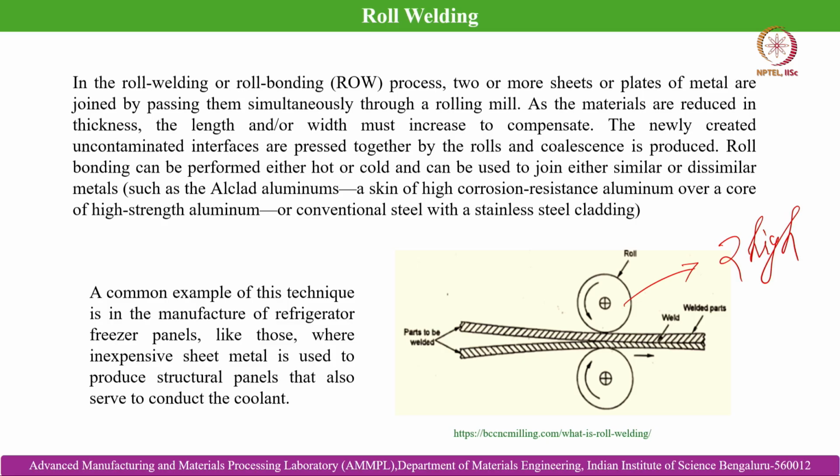So this is also a technique of cladding. Although nowadays there are advanced cladding techniques such as laser cladding which are very useful to make claddings with much reduced thicknesses, this is a technique where a significant thickness of the cladding layer is needed, and it is used when we are talking about sheet metals or thin sections.